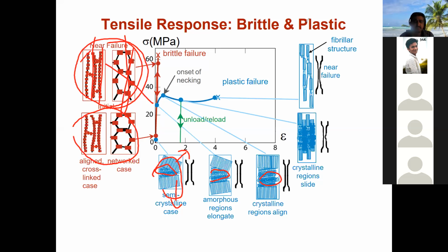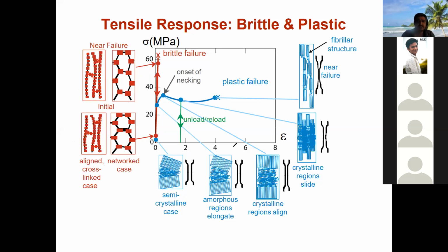And next, if you take a plastic material, look here. At zero stress, you're not applying any stress, and nothing is happening. Slowly you apply stress. This is under the elastic range, still under the Hooke's limit. When you apply stress, your amorphous region increases. You see the area here and here keeps on increasing. When you release the stress, it will come back to this position, right?